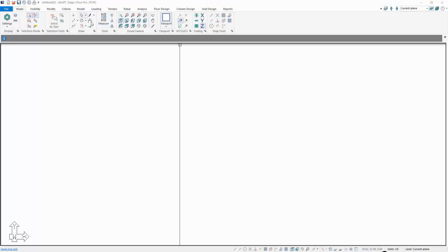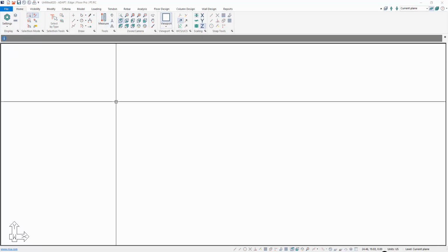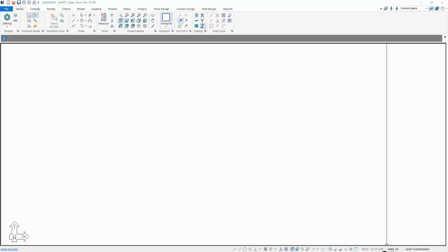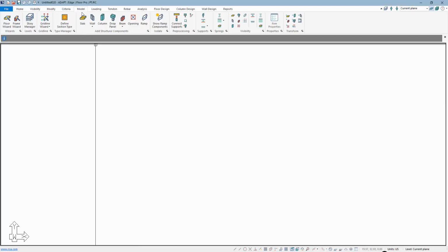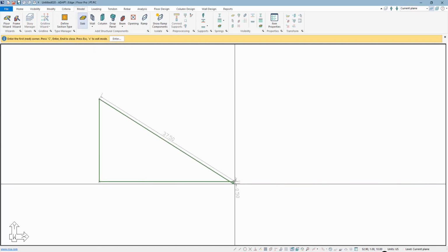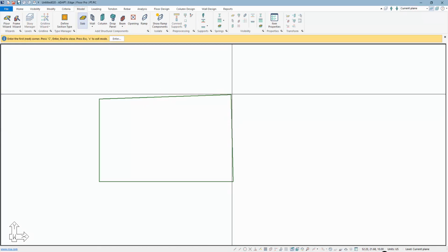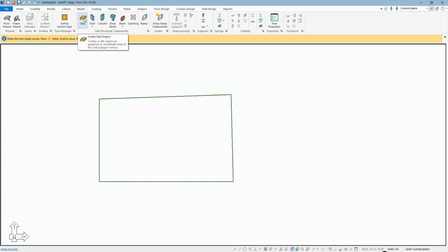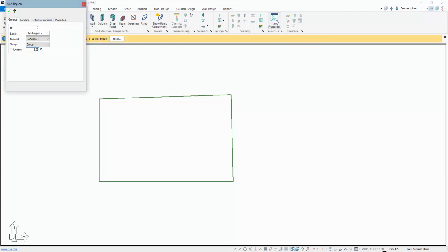And what we're going to do is, by default, the default thickness of a slab in this case is 8 inches or 200 millimeters in SI units. So here we're opened in US units. If we go to model, and let's say we model a slab of 8 inches thick, and in the same instance of use of that tool, I'm still actively engaged in that tool, I'm going to just change the properties now to 24 inches.